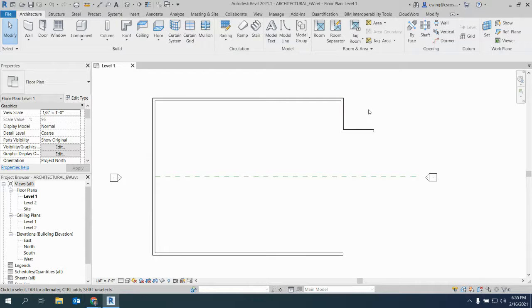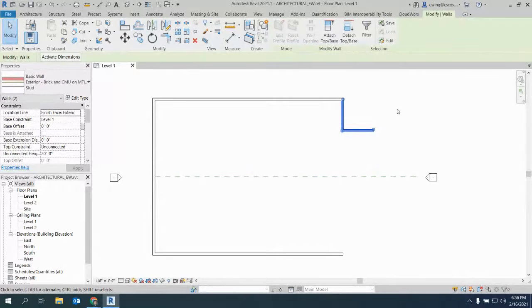If you pick a window, starting from the right to the left, I should say if you pick a box, there's no windows in our model yet. If you pick a box from the right to the left, notice that all you need to do is come into contact with one of these elements and it becomes selected, right? If you pick a box from the left to the right, notice the behavior is different, right? You have to have the entire object ensconced within that box for it to become selected. So with one of those three methods, go ahead and select these two walls.